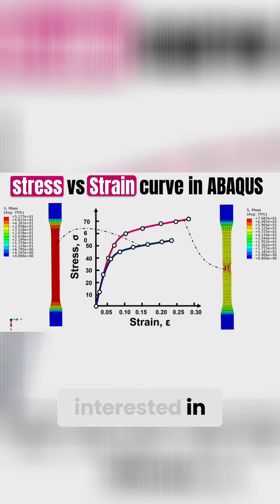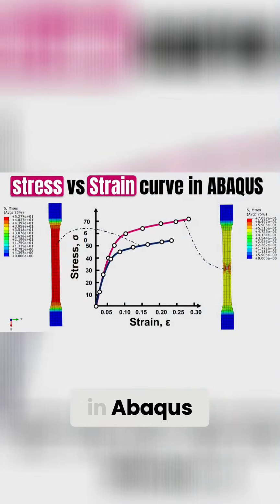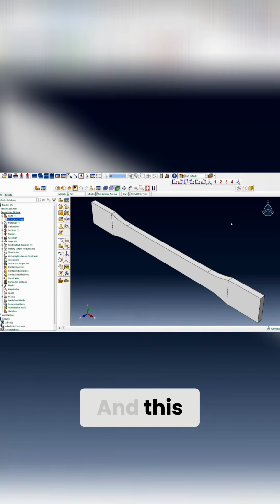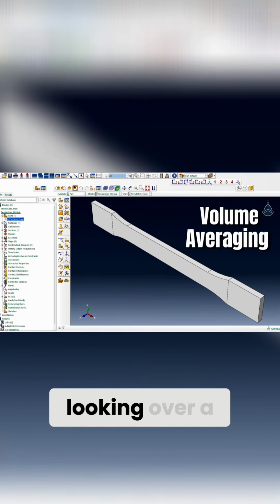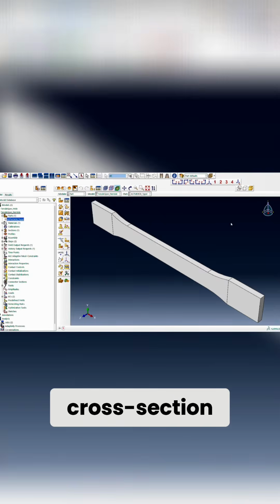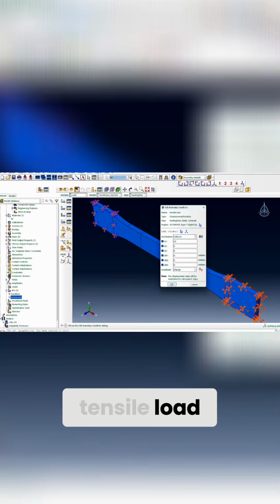If you're interested in generating the stress strain data from a simulation in Abaqus, this is one of the ways that you can do it. This particular method involves you volume averaging the parameter that you're looking over a defined cross-section. So if we look at the fix, it's fixed at the back, and also in the front, we've got our tensile load. Okay, before we run that, we need to mesh the domain.